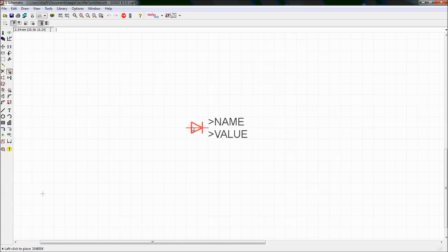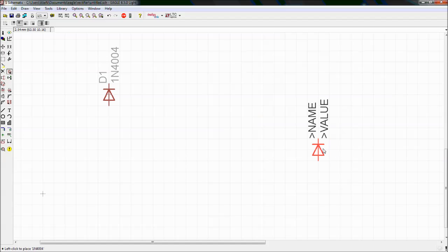It's up to you where you want to put it. Now I will suggest you just play around this center, which will help in the Gerber file. The component places are defined from this center, so it is very important that you always play around the center. Now the component is in your hand. To rotate it, just right click once. I am keeping it vertical. Now I wish to put it over here, just one click. Okay, it will place the diode.